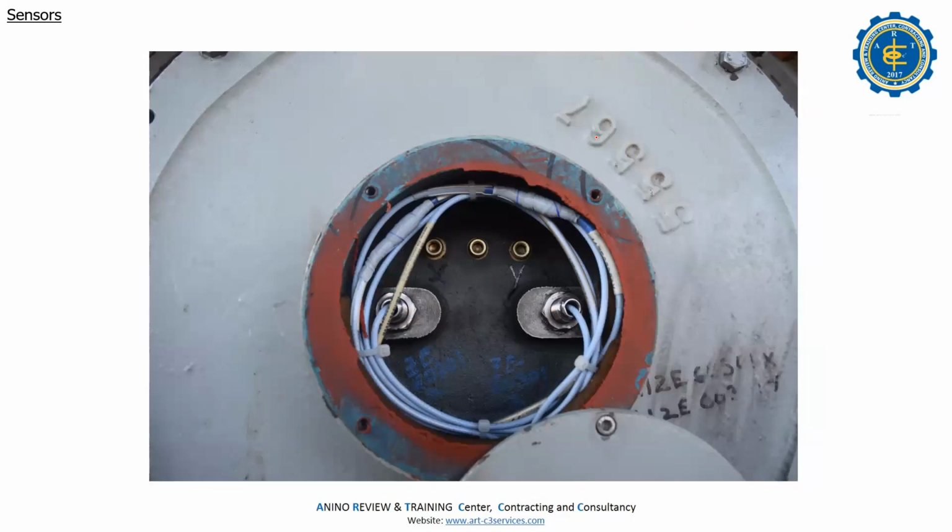So this one, the proximity probe. We have X and Y. The trip here is normal. In the old way, in the tripping, you have 2 out of 3, meaning with the 3 probes, if 2 hit alarm, it will trip.